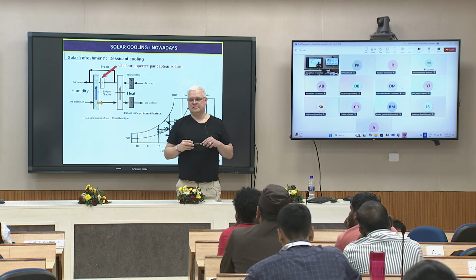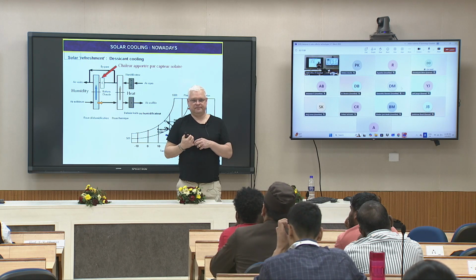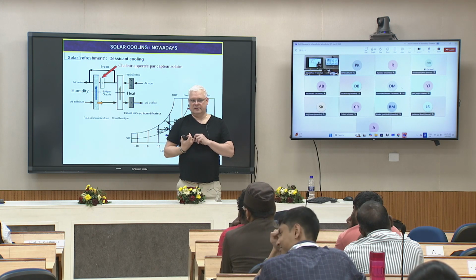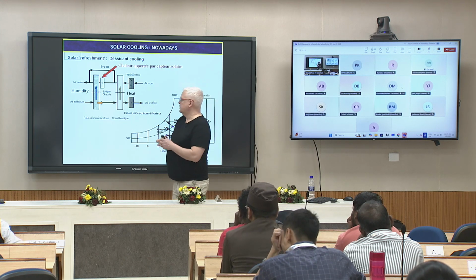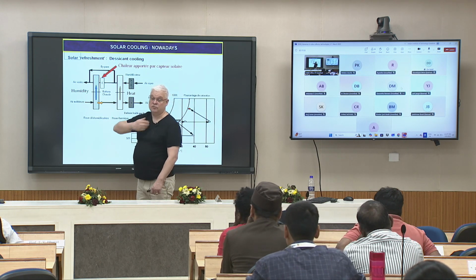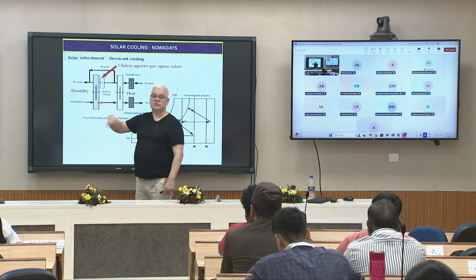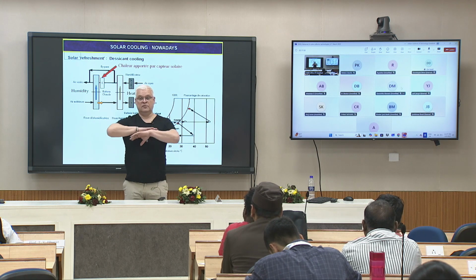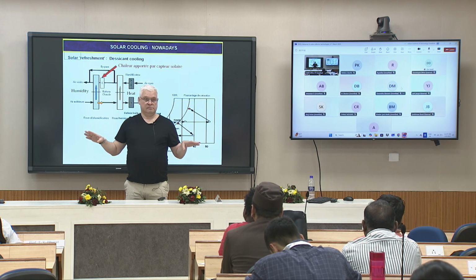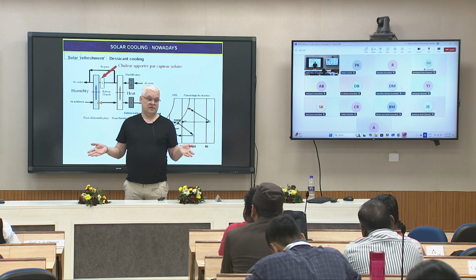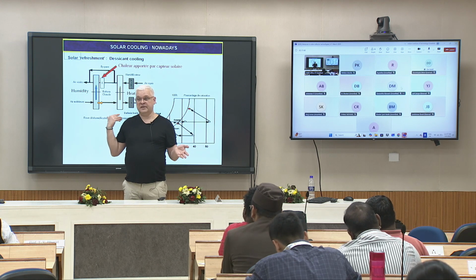Why? Because we want to dry the desiccant wheel. Because the humidity is collected here, we have to get rid of it. If we don't get rid of this humidity, at a certain stage the wheel will be fully saturated. And if the wheel is fully saturated in humidity, the process can't operate anymore.